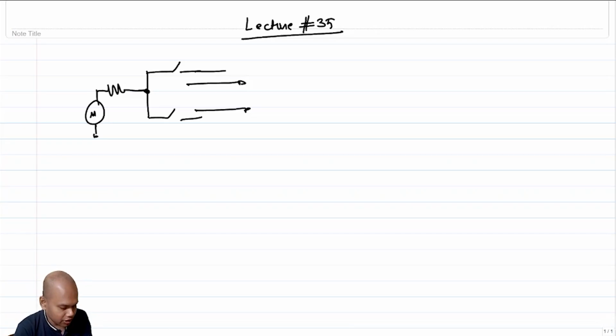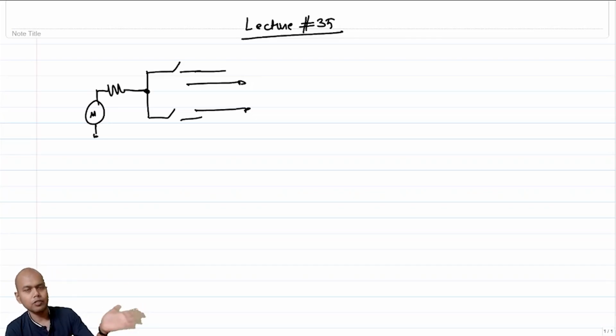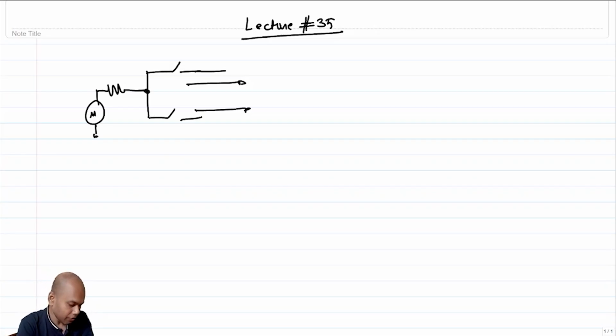We also saw that conversion gain is contributed by only C1, whereas noise is contributed by the summation of C0 squared, C1 squared, C3 squared, and so on, right? So that is fine. Note that while doing all this analysis, we only assumed that the noise is coming from this source, right?